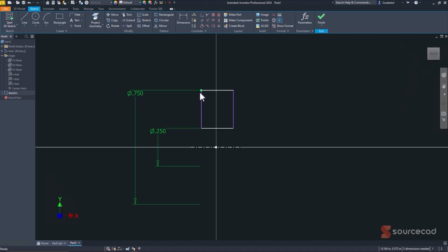Now, say I want this on the center line again, going this way. I could project in, if I wanted to, this axis, or I can utilize a construction line. Let me exaggerate a little bit. I'll drag it out to the side just to show you how. If I click a line and make it a construction line, I could go from the center point, and I can go up, and I can just hover the line, and you'll see when it turns green, that means I'm on the center point.